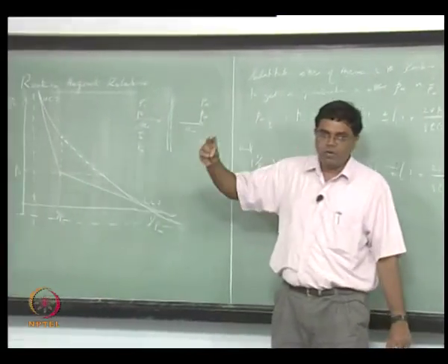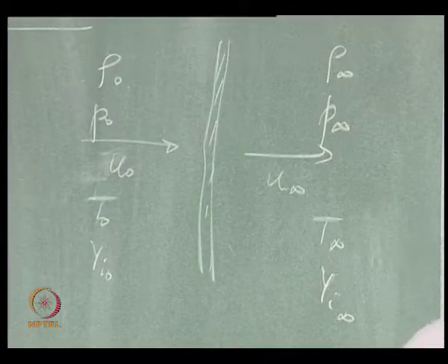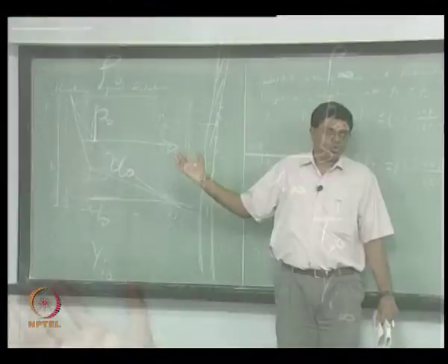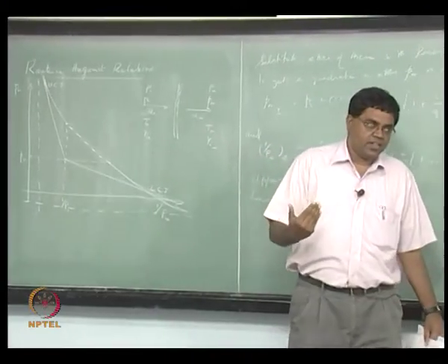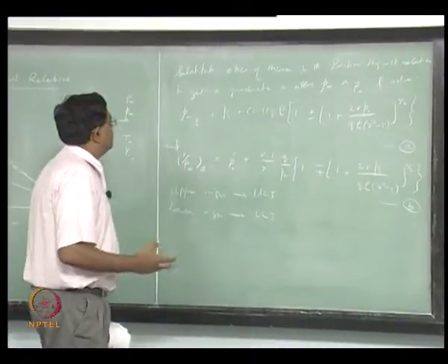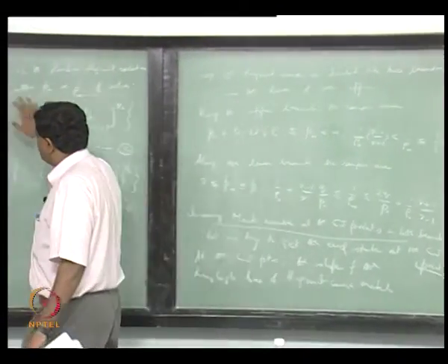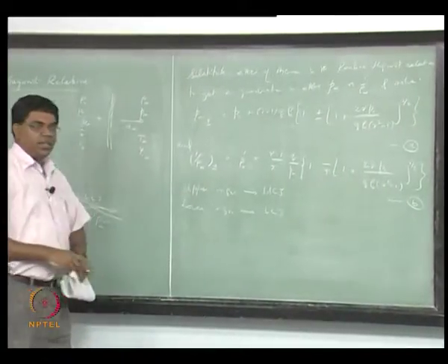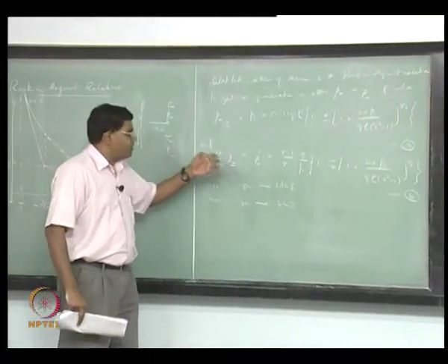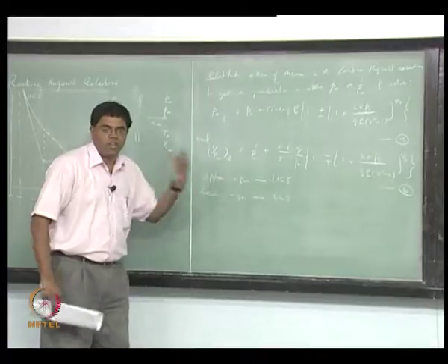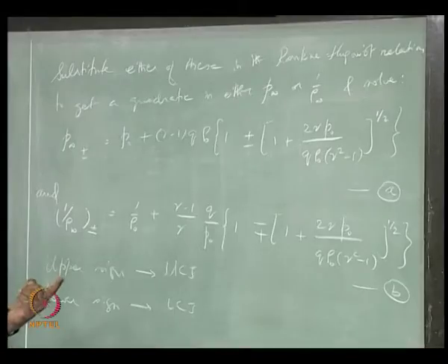That means we are looking at m dot, through which we will try to look for rho naught u naught, and m dot doesn't show up in the Hugoniot curve, it's showing up only in the Rayleigh line, right. So we should now go back to the Rayleigh line. We have substituted the slope matched information into the Hugoniot curve to get this, but can I now look at how the Rayleigh line is going to be if I plug these coordinate points into the Rayleigh line and then get an m dot information through that? You see what I am saying, okay.